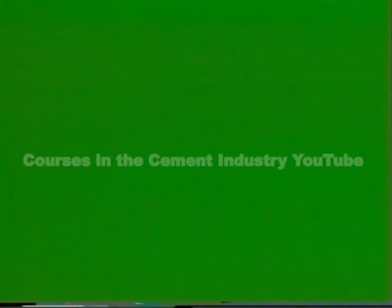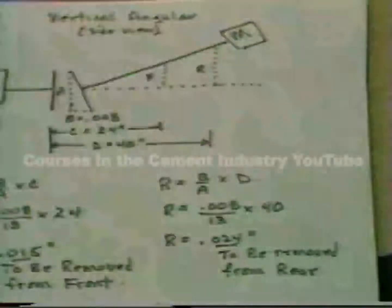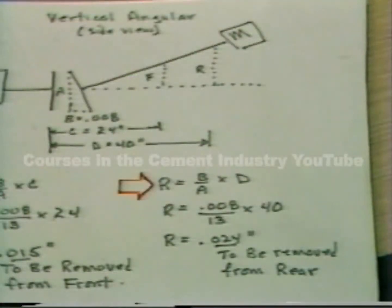Assuming we're calculating front feet shim changes, which we call F, we'll need to know the diameter of the dial post, which we call A, the amount of vertical angular misalignment, which we call B, and the distance from the dial post to the front feet, which we call C. The formula is then F equals B divided by A times C. The same basic calculation is done for the rear feet, except we use the distance to the rear feet in the formula instead.